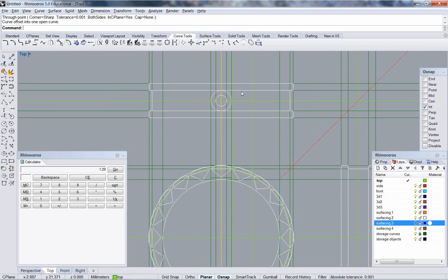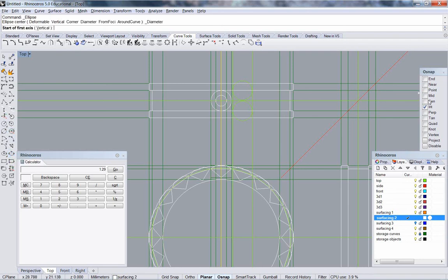In order to draw an ellipse in Rhino, we need a center, either a center of the ellipse or a center for the diameter. We have neither one here. We need to create it. I'm going to make circle diameter. Draw a circle here and a circle here. These are just construction lines. And then we're going to use them to do an ellipse diameter.